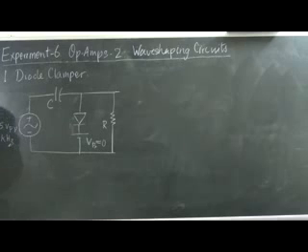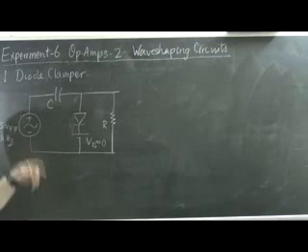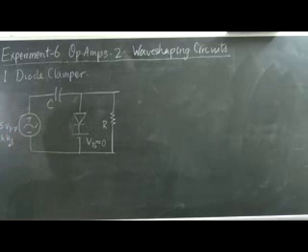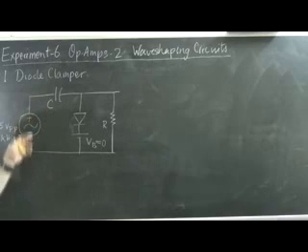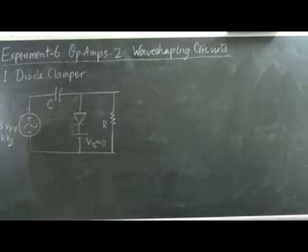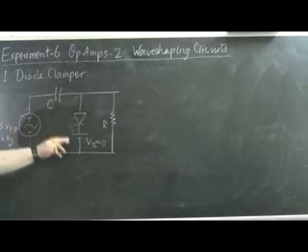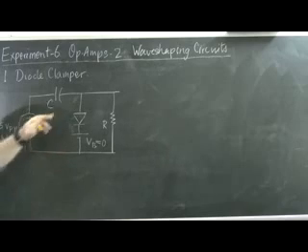Initially, current will flow through the capacitor and cause it to charge. The capacitor voltage is now being charged through a circuit of almost zero resistance. The only resistance that is present is the minor internal resistance of the source here, and the forward resistance of the diode.